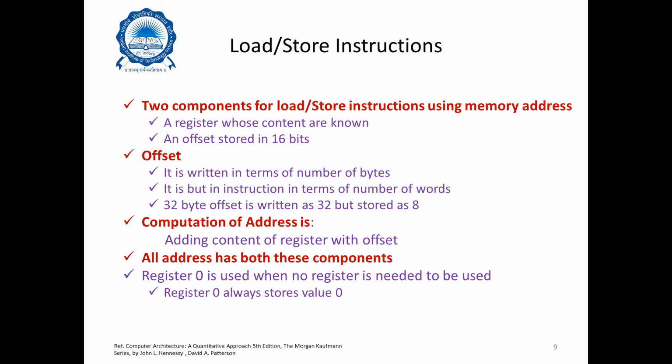So imagine that somewhere you have an instruction LW $T0, 1200($T1). The memory location will be 300, basically the array's 300th location, because every location is able to store 4 bytes, right? That's the reason when we have 1200 it becomes memory location 300. So that 1200 becomes the offset. We write it as 32 but we store it as 8. That's what I'm trying to say here.